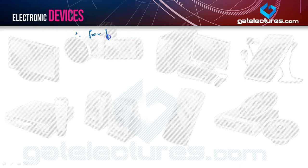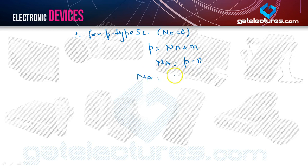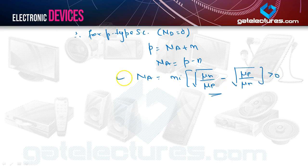So for p-type semiconductor, you have Nd equal to 0, so we can say that P is equal to Na plus N. So we can get Na as P minus N, and Na as Ni times the square root of mu n by mu p minus the square root of mu p by mu n, which is a positive value. So this expression is good. This is resulting in something that we can expect. Okay, now let's do the analysis of these two expressions.